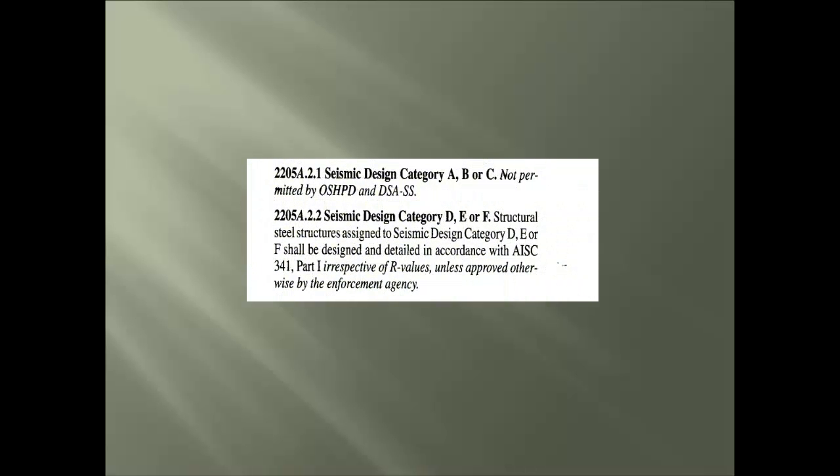Once again, we could spend days breaking down each important part found in this chapter alone, but we will only review key items that you need to be alerted to, and one of those is the definition changes with seismic zones. Now, if you are not in California as you participate in this seminar, the word earthquakes probably doesn't grab your attention as much as the words tornadoes or hurricanes. But here in California, we have different zones of movement from earthquakes, and in the older codes, the terms seismic zones 1, 2, 3, and 4 were used, with 1 being the least and 4 being the most severe.